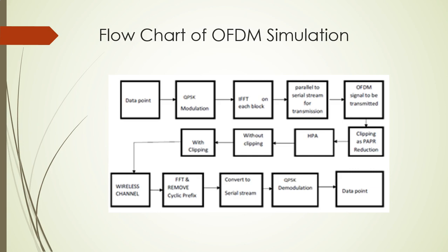So, an inverse Fourier transform converts the frequency domain data set into samples of the corresponding time domain representation of this data. Specifically, the inverse fast Fourier transform is used for OFDM because it generates samples of a waveform with orthogonal frequency components. Then the parallel to serial block creates the OFDM signal by sequentially outputting the time domain samples.